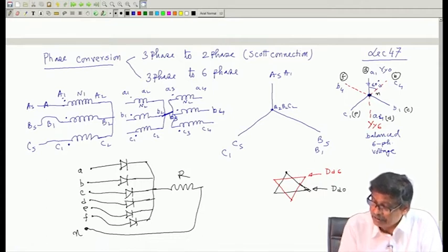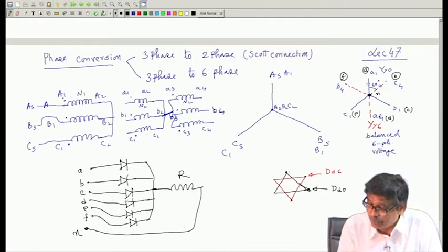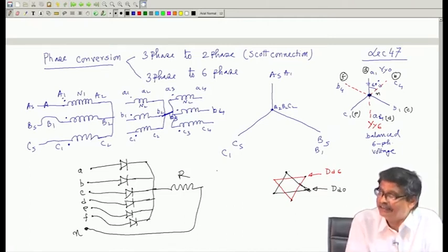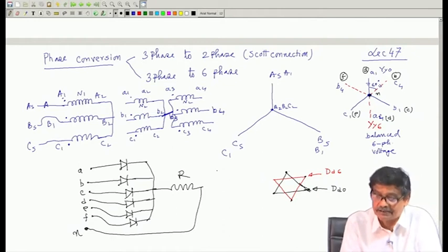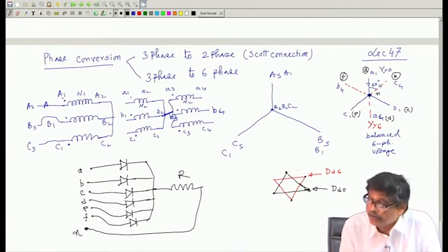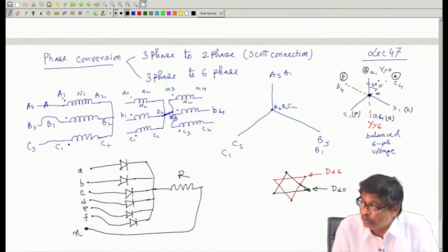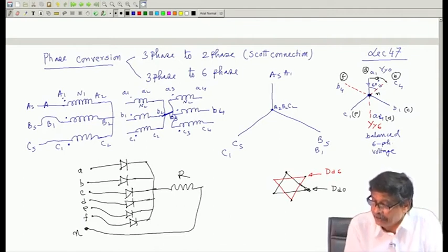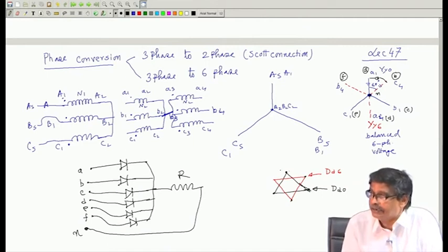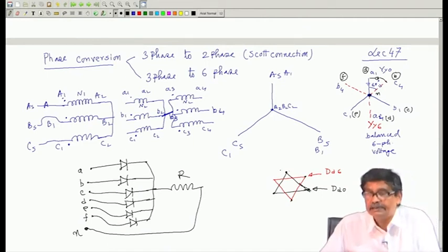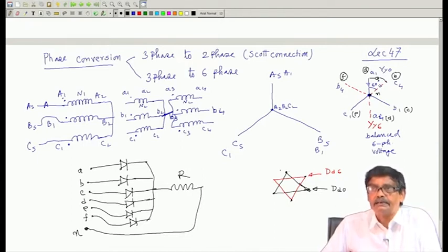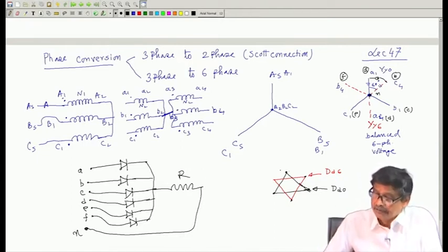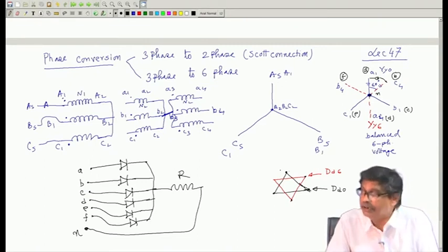Then also these terminals, of course, there is no scope for connecting neutral now. This is delta, this is delta. Where is its neutral? Nothing to be joined here, as I have joined here. So, if you connect a voltmeter, for example, here, even when no load is connected, voltmeter will read this much. But if you connect the voltmeter here, circuit is not completed. So, what is to be done? You will get balanced voltages here, provided load is connected.